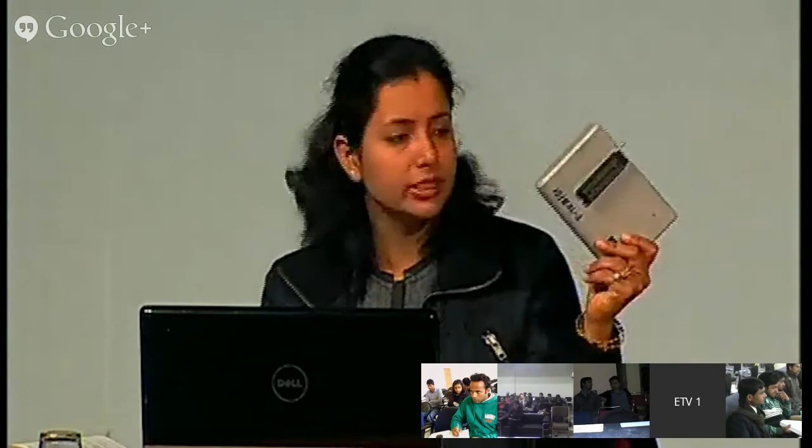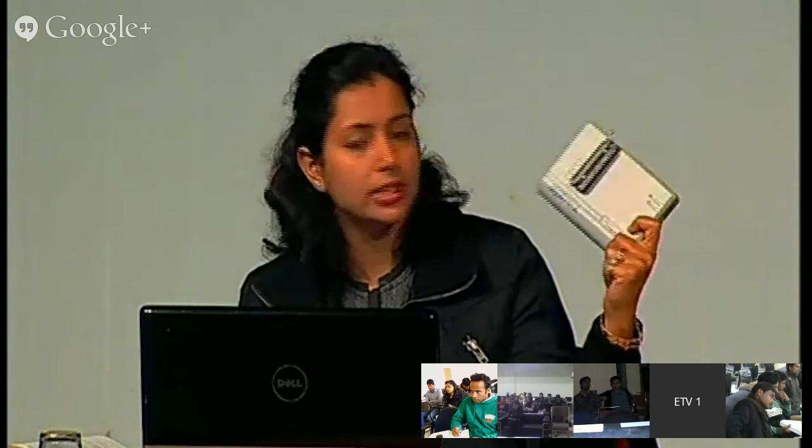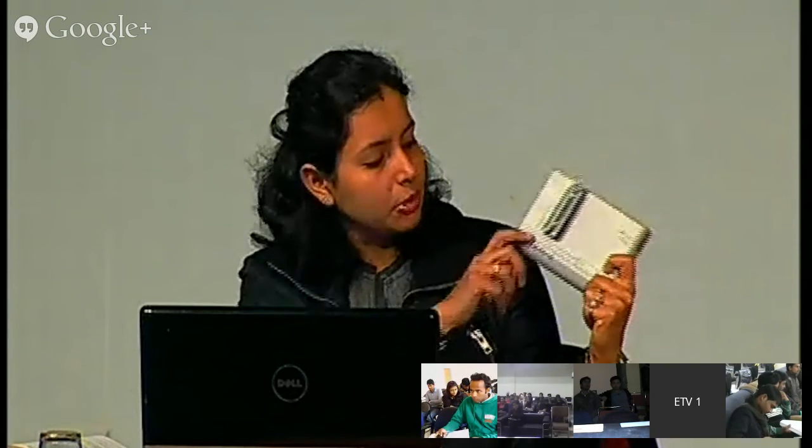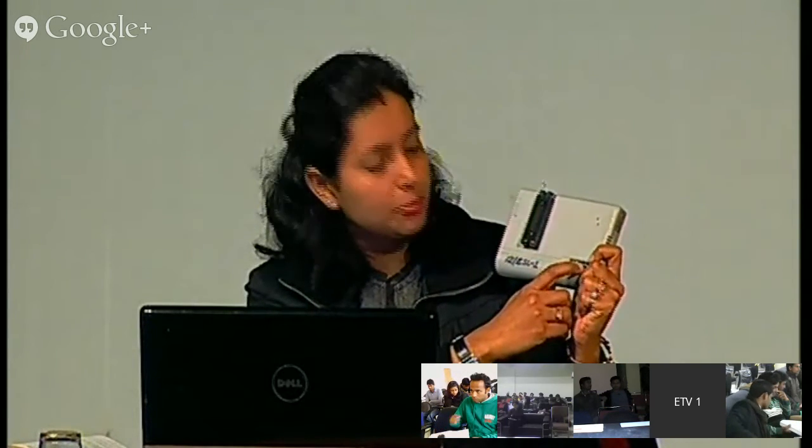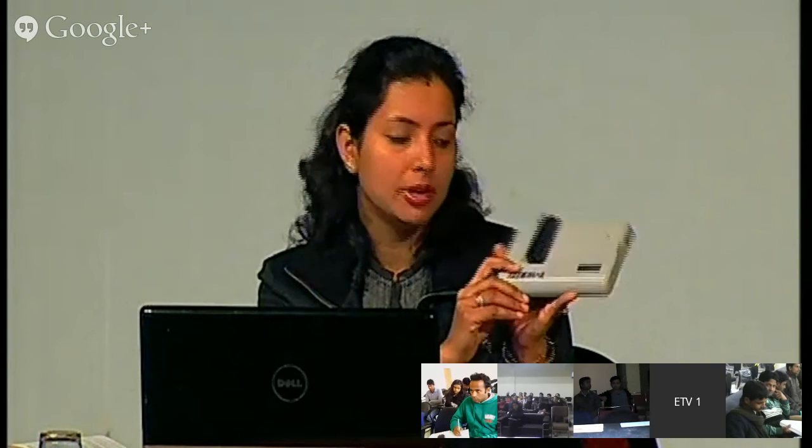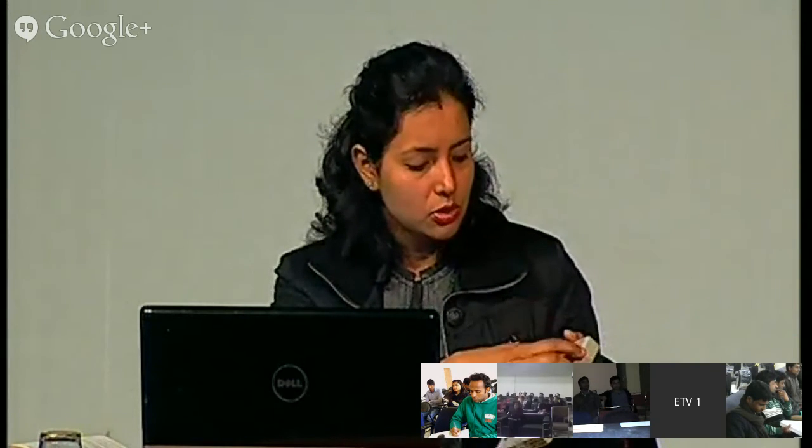So this is the universal programmer. This can be of different companies. For example, I have one from Unipro 110. So why is it called a universal programmer? Because any kind of IC or any kind of controller you can put here and you can burn it.